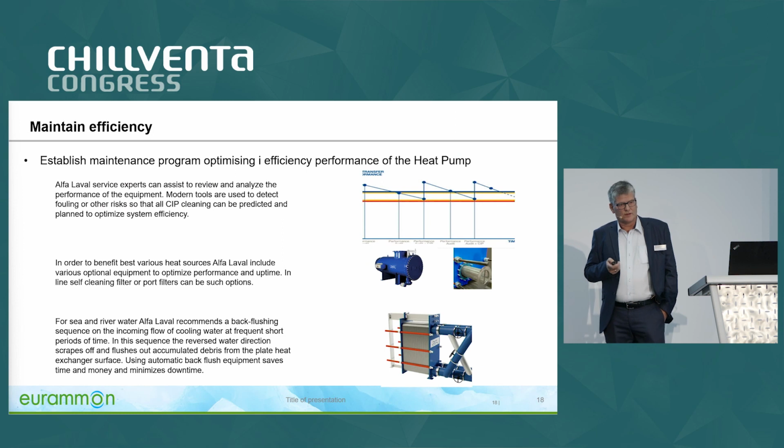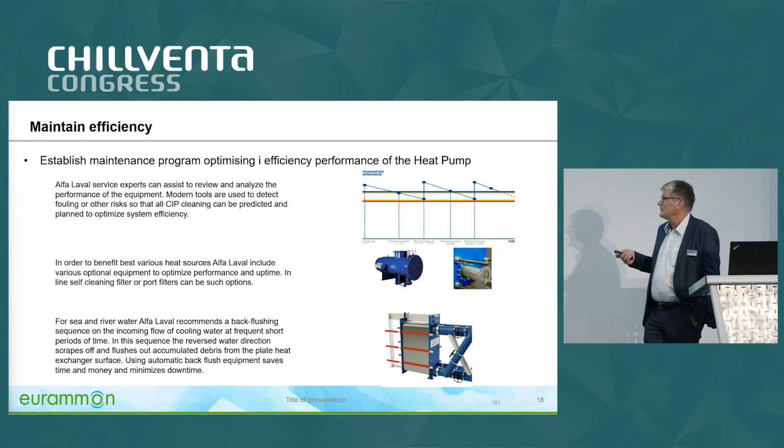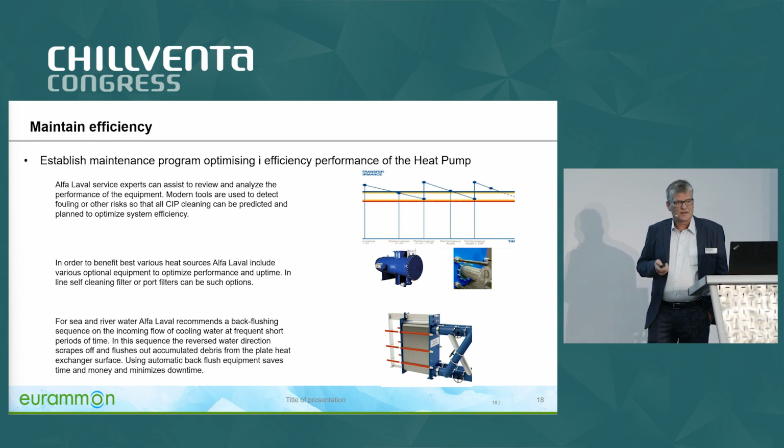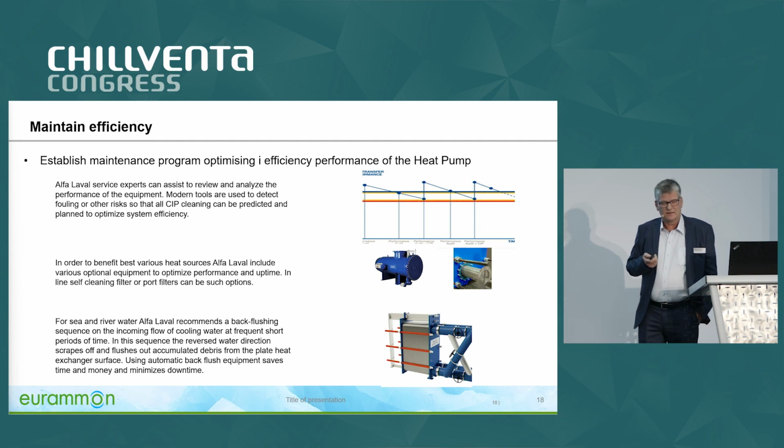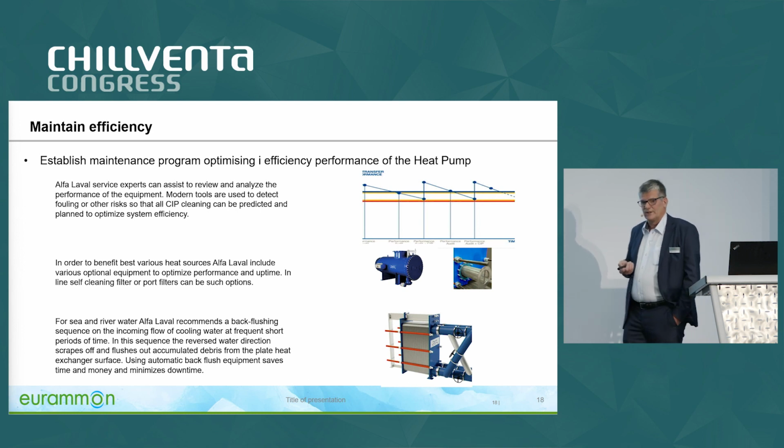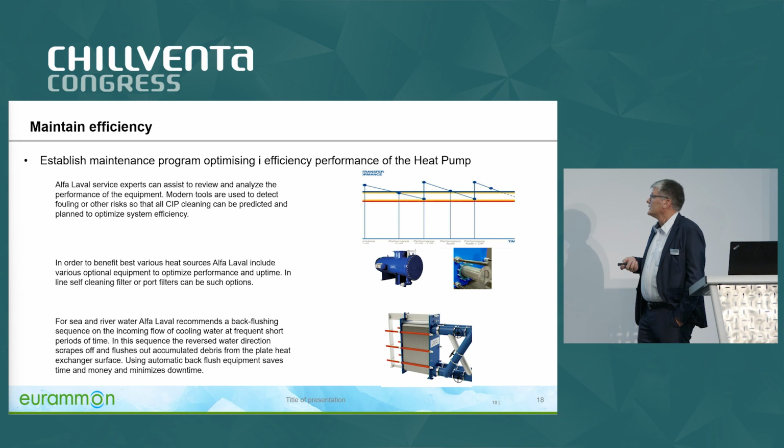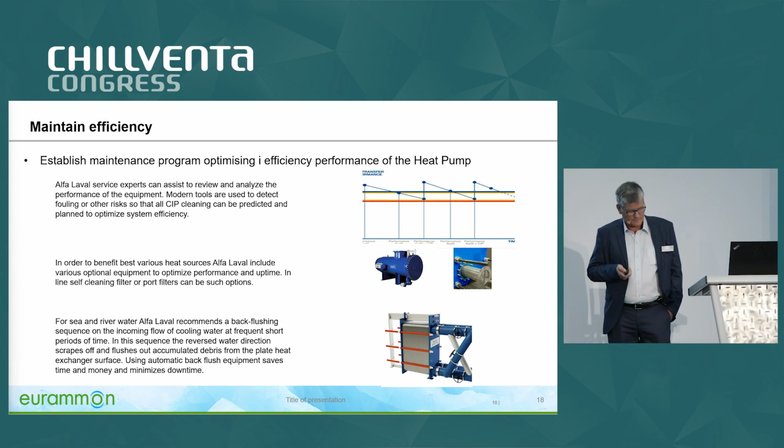But of course, we can also introduce maintenance plans so that we have CIP cleaning for scaling at regular times. We can measure when that is needed from temperature differences or from a visual look at the heat exchanger.